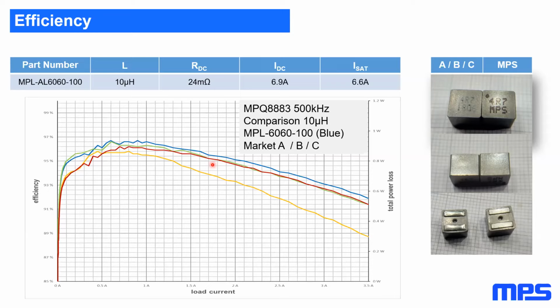All right, and then let's see. When calculating a switching regulator efficiency estimate, it is easy to model the DC losses of an inductor because they are related to the RDC and the inductor current. But calculating the AC losses is hard because it involves parameters that are not very well known or shown in a datasheet. Any recommendations on how to model AC losses to calculate switching regulator efficiency in a simpler manner?